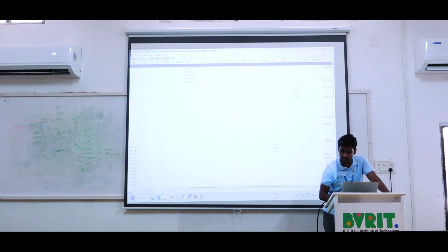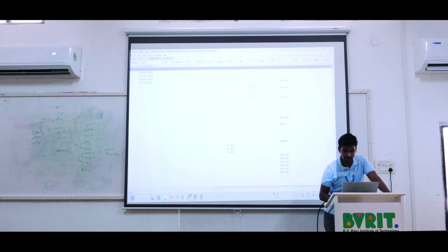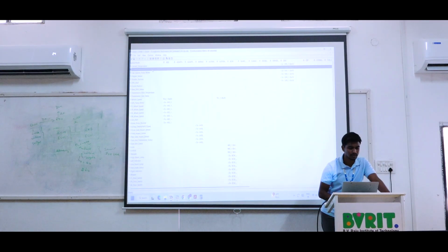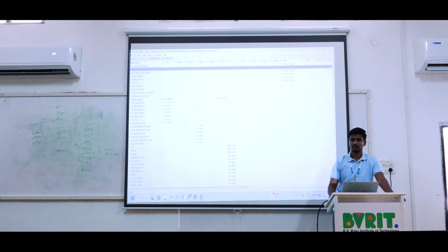Now we can see that it is received by the instrument cluster. Yes, the instrument cluster. We are not receiving coolant temperature; instead we are receiving engine speed. So engine speed is received by the IC. So these are all part of the center. Engine coolant temperature also goes to the instrument cluster, right? Yes, sir.